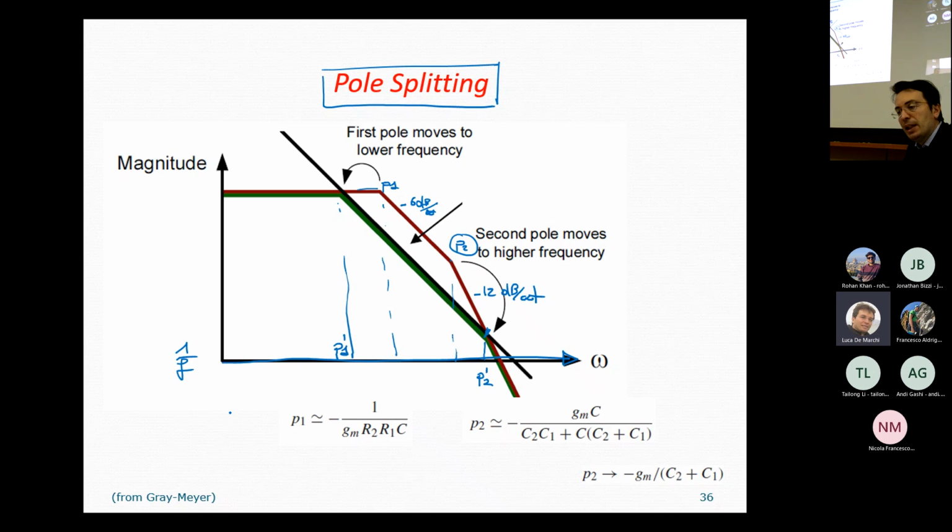If we have a situation like this one, this is quite interesting, because we can apply the fact that again, we have an inverse proportionality between the gain and the frequency. This trend, which looks linear in a logarithmic plot, is actually a hyperbolic trend.